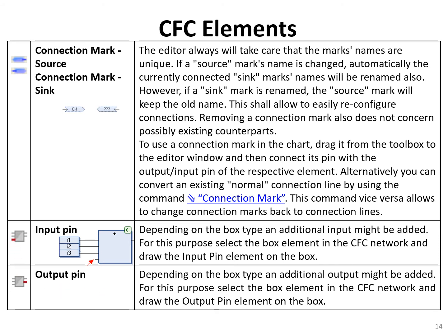Output pin. Depending on the box type, an additional output might be added. For this purpose, select the box element in the CFC network and draw the output pin element on the box.